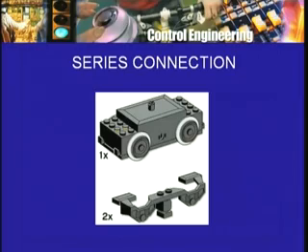In electric locomotives such as those operating in a city like Mumbai, the motors which are used to drive the wheels are DC motors with a series connection, whereas in many industrial applications the motors will be DC motors with a shunt connection, or even with what is called a separate excitation. So what is the difference between a series and a shunt connection?